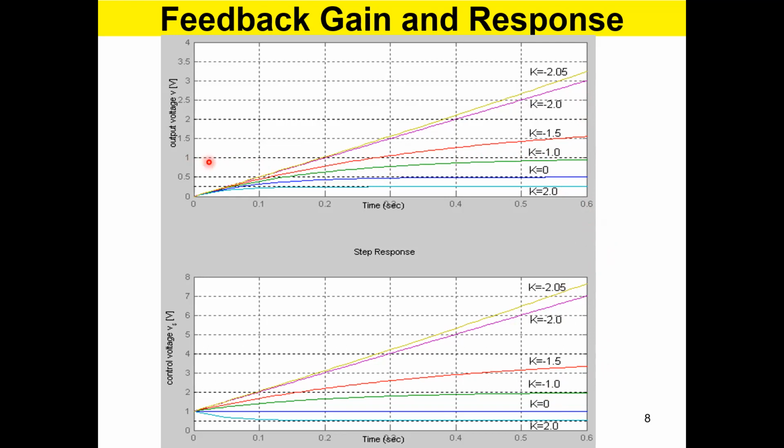Because what we are doing is the unit step response. So input is 1. So the output is 1 as well, right? So when DC gain is 1, when you clamp the system to have unity DC gain, this is what happens. Output is equal to input in the long run.